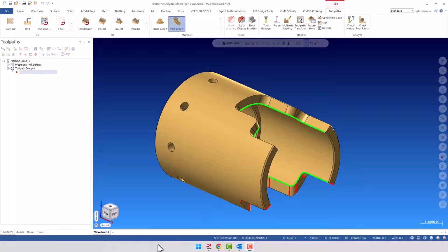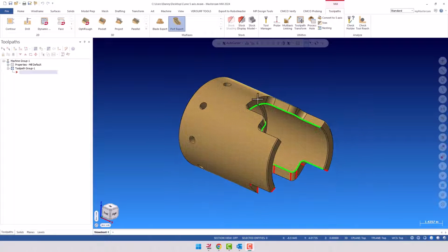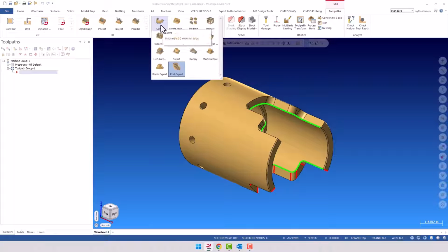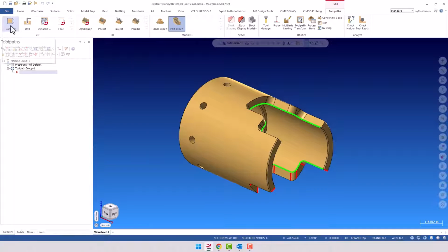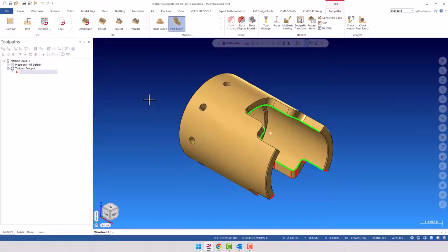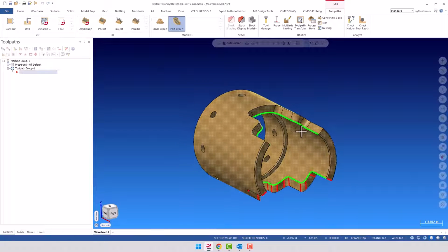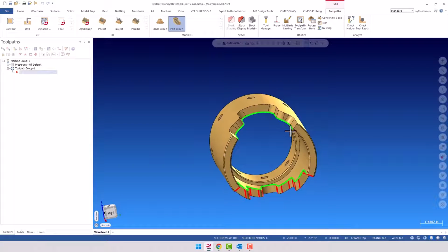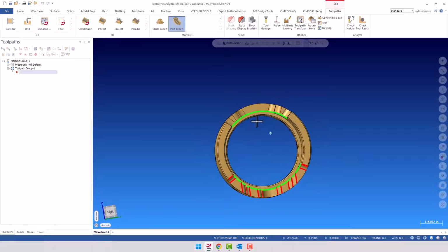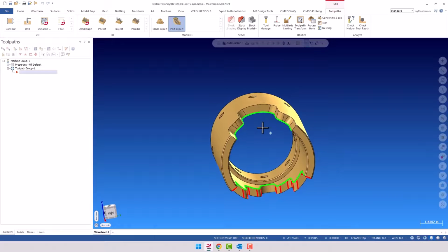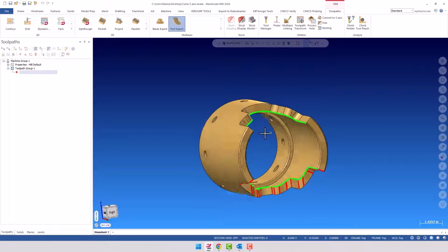All right. So the first thing I have is this part up here, and the first thing we're going to cover is curve drill 5-ax, versus contour. If you're familiar with Mastercam, we could do contour and do an axis substitution, say for this shape right here. See the shape, everything kind of points toward the center, and it would not be hard to take the tool and tell it to wrap around this geometry.